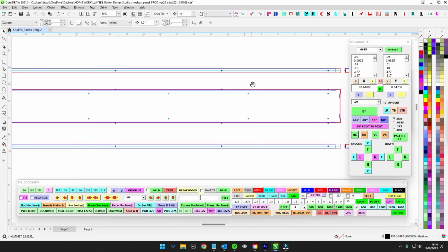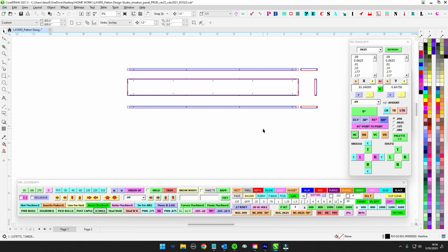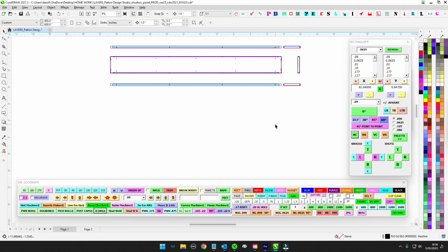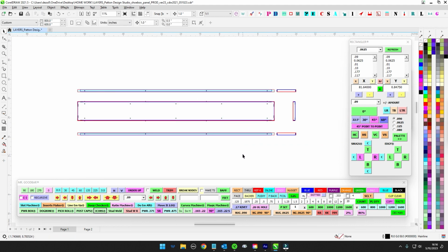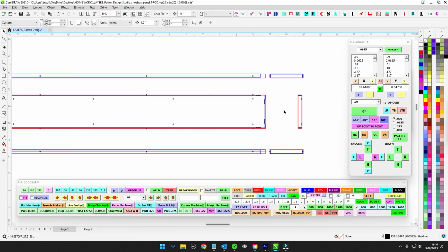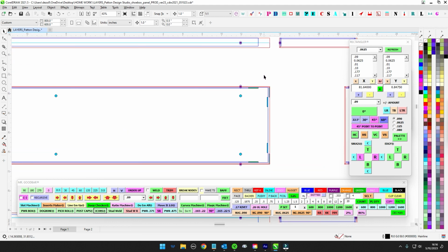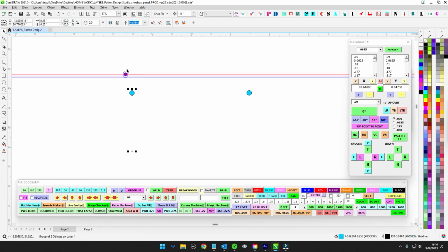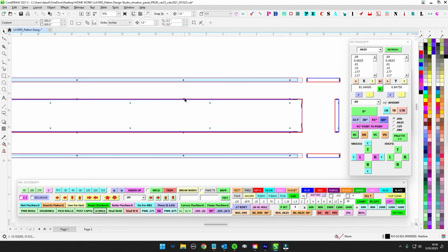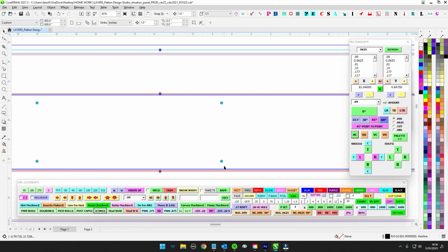When it comes to shoebox, if you're talking a bigger shoebox, like a cabezon sign where you've got a lot of weight hanging off of it, I will always default to a lot more mounting. It's better to have more screws into the studs and into the wall than less, because it'll stay up there better. The other thing is to make sure that, especially with these bigger signs that have more weight, when it comes to engineering and physics, you want to keep your mounting screws as close as you can to these screws, because the path that has to travel means stress put into the framing.